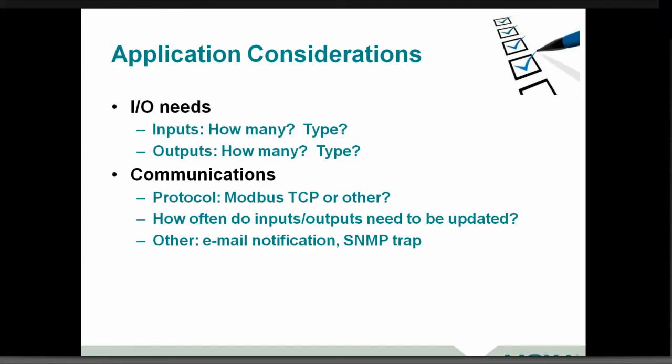Also on the communications, it's good to understand how you want to interact with those field devices. How often do you have to read those inputs and outputs? What is that process to update those? And this is where it takes a little bit of discussion with what you're going to do on the software side of things. And lastly, are there other communication needs? We've simplified a lot here today and talked about more of an industrial automation centric view, utilizing MES type software for your manufacturing usage, or SCADA software, or HMI software.